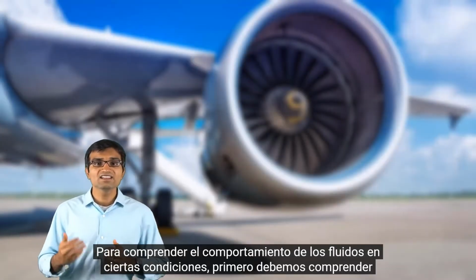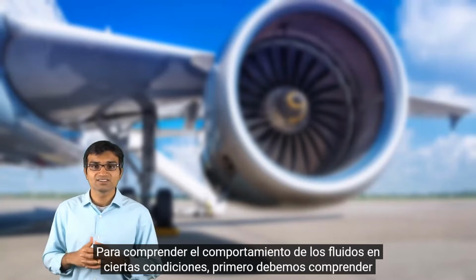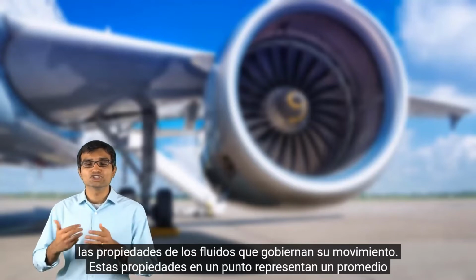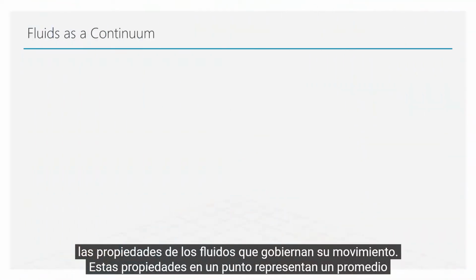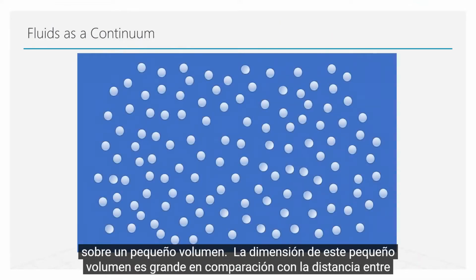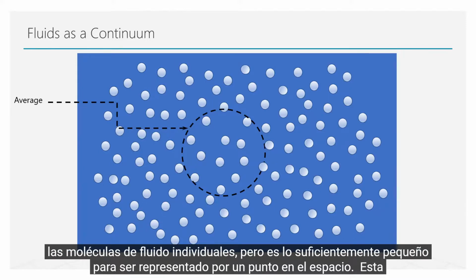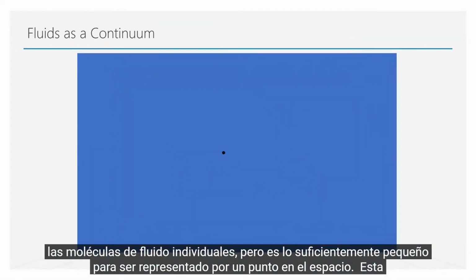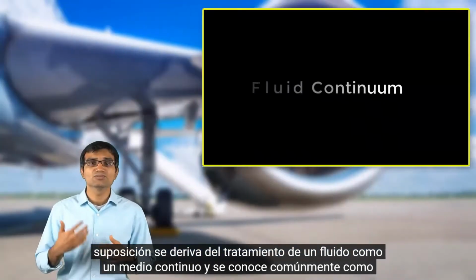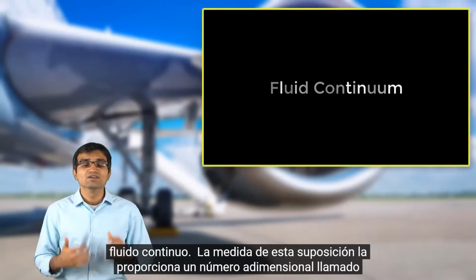In order to understand the behavior of fluids in certain conditions, we have to first understand the fluid properties that govern its motion. These properties at a point represent an average over a small volume. The dimension of this small volume is large compared to the distance between individual fluid molecules, but is small enough to be represented by a point in space. The assumption stems from the treatment of fluid as a continuous medium and is commonly referred to as fluid continuum.